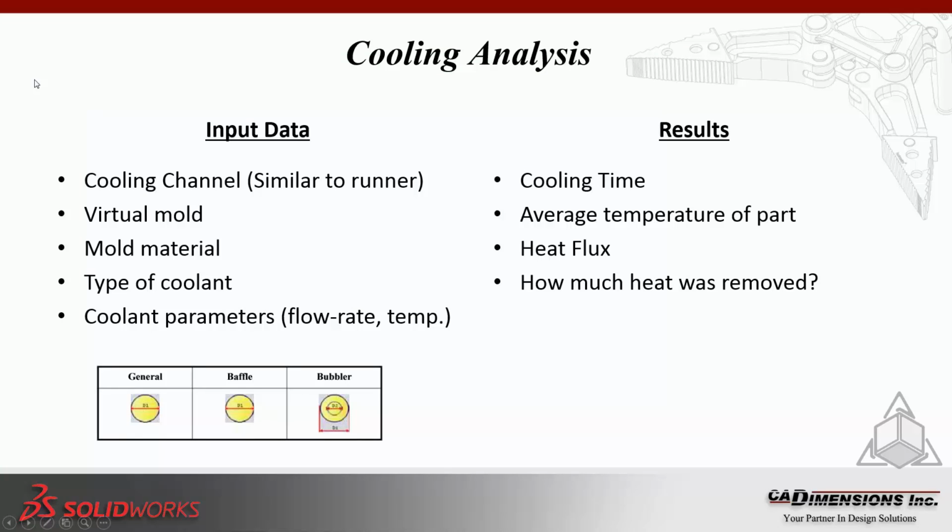So in terms of input data, we have our cooling channels. How do we set up those cooling channels? So it's very similar to the runners. Basically, you sketch it in and you specify the diameter, and it creates those cooling channels. You can specify the shape of the cooling channel.